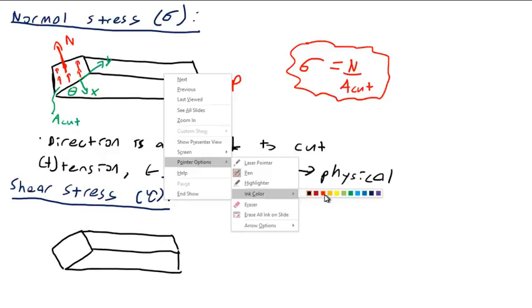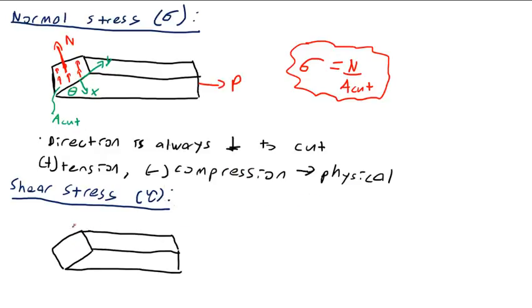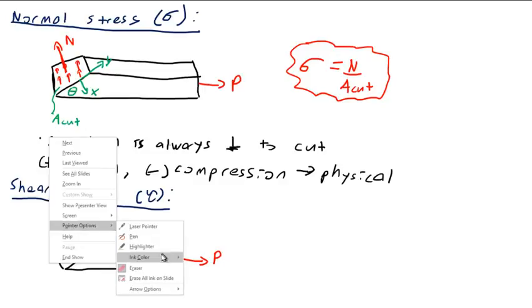And we have a whole bunch of shear stress arrows, and these will come together to form the overall shear force. So we have the P here. We have many shear stress arrows across the surface of the cut. And all of these together combine, along their centroid, to form, oh, there should only be one arrow there.